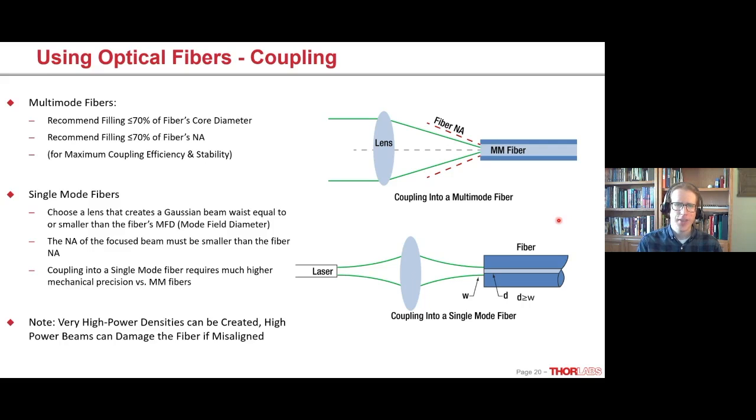And then a less straightforward way to look for fiber breaks is what we call an optical time domain reflectometer, or an OTDR. And the idea there is this is a machine that's going to emit a very short pulse of light into the fiber.